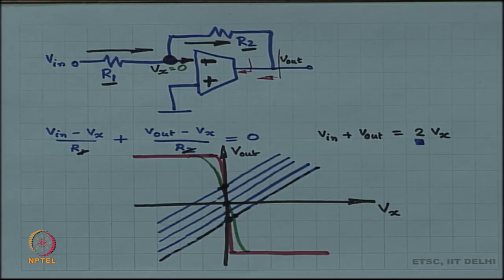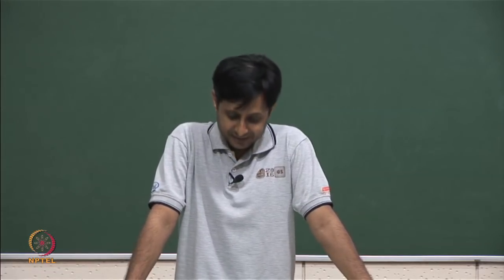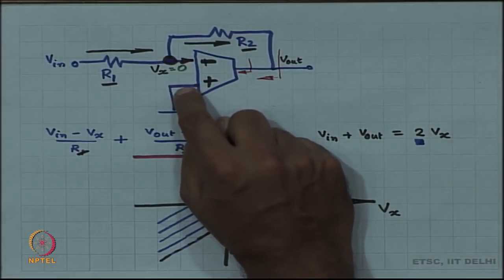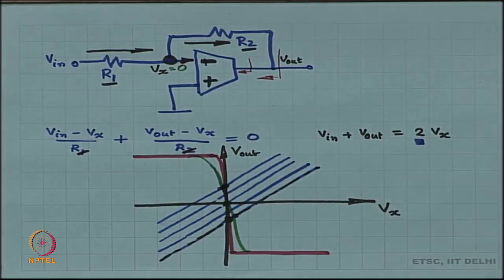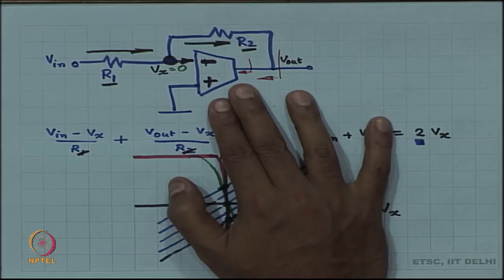So, this answers a few things. First of all, it answers the question, why are the two terminal voltages more or less equal? This graph should answer that. Number 2, you should be able to understand now why an op amp and OTA are very similar and what is the difference. The op amp has a low output impedance to start with, it is a voltage controlled voltage source.